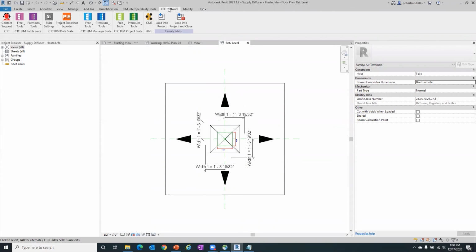For those original shared parameter files, I would almost always keep a backup copy as well, in case you do lose it. Put it in a heavily secured area, maybe where you have access to it if you are, say, the BIM manager. Make sure that it is well protected.